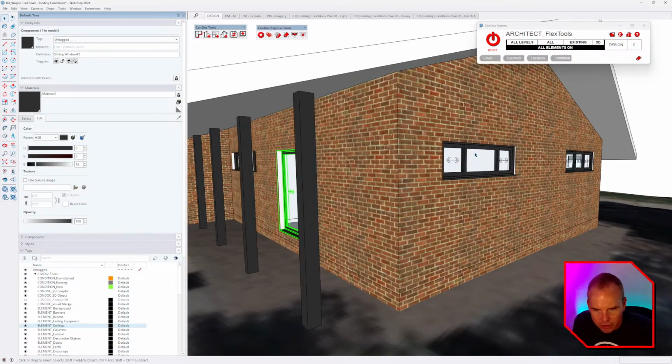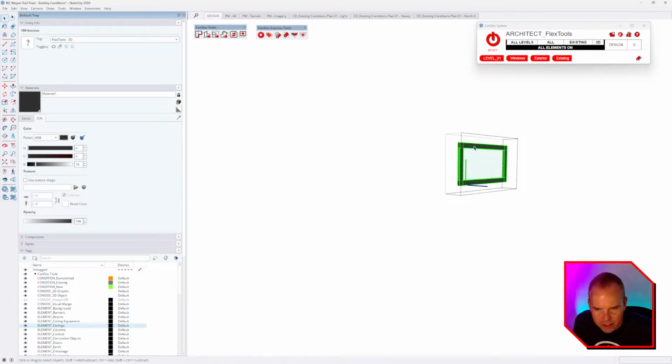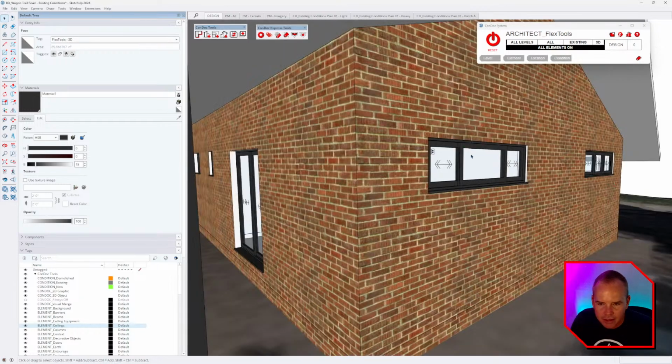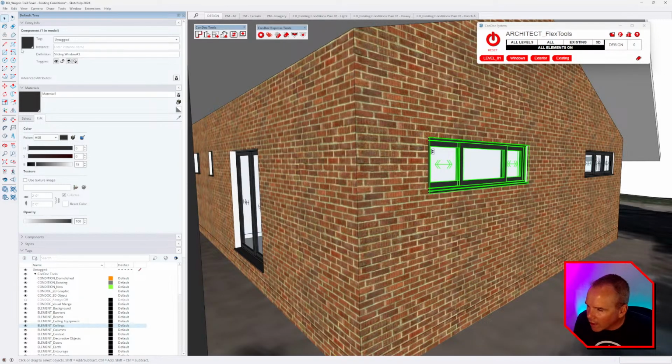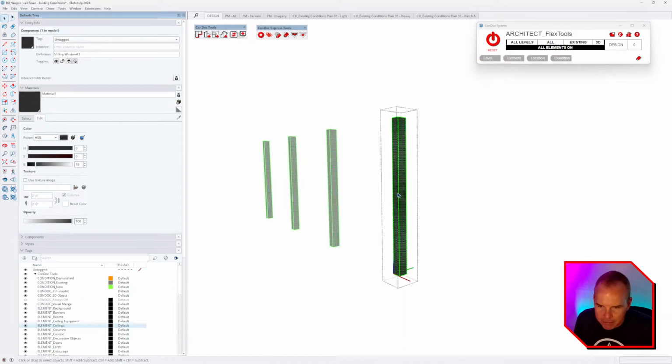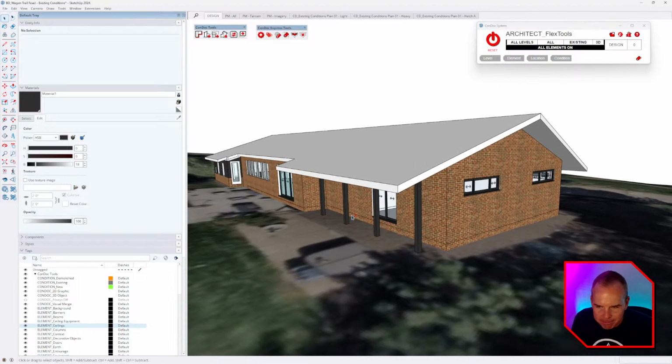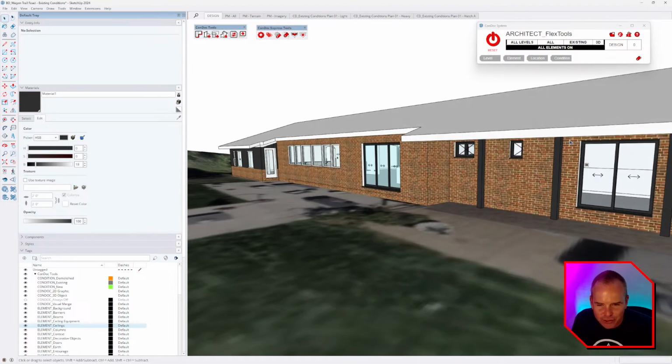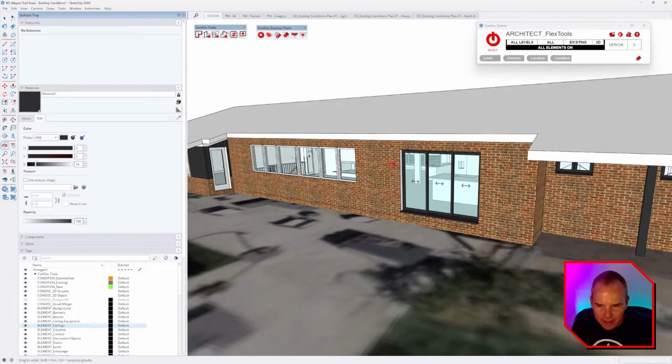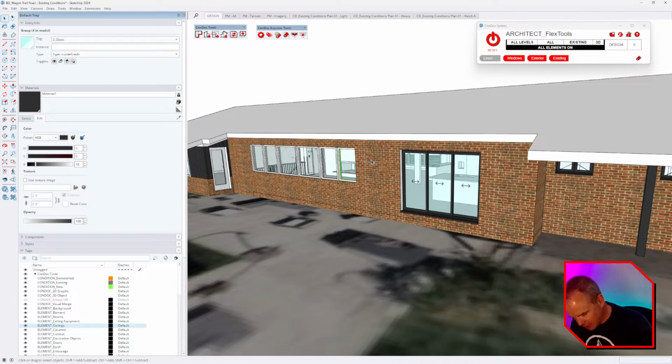So basically, whenever you have a surface in here and it has the default material assigned to it, it's going to inherit whatever texture is assigned to the outside. Best practices in SketchUp is to drill in and only assign textures to a surface, but I know that this is going to work out okay for me. All right, so let's isolate.